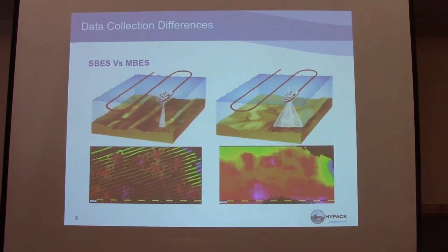When you're with the multi-beam, does your overlap really depend on the depth of water? It's like with side scan, you try to get 50 or more feet of overlap when you put your plan lines in. So say if you're running 50-foot plan lines, when you're with multi-beam, should it be based on your water depth to get the coverage, or should you just run the 50-foot plan lines?